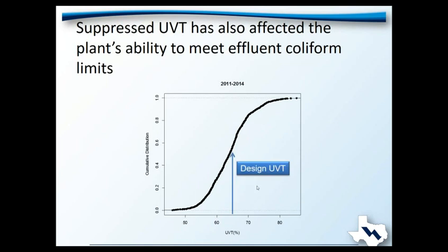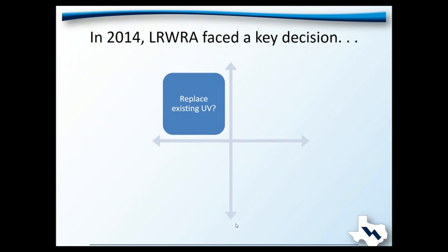For many facilities designed for secondary effluent, a typical design UVT can be 65%. But when we look at historical Adams Field UV transmittance data from their online UV transmittance analyzer, what we see really is a 10th percentile where, if we were to go back in time and relook at UV applications for this facility, it might be designed for something like 55% UVT, or to deliver a minimum UV dose at a much lower UVT. So that was particularly challenging for this facility as well.